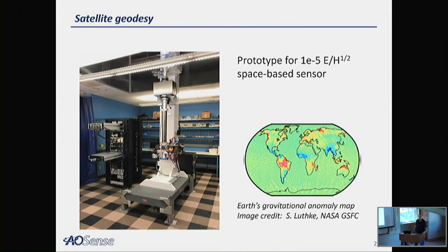So I want to conclude by saying that not every sensor is going to benefit from this. For the ones where all you're looking for is accuracy at the output, and you don't need stability, don't bother using state squeezing. It's not going to improve your accuracy. It's just going to help you integrate down to your, quote, flicker floor or the observable faster. If you're noise starved, like LIGO was, state squeezing is an appropriate thing to do. If you're not noise starved, don't go through the hassle.